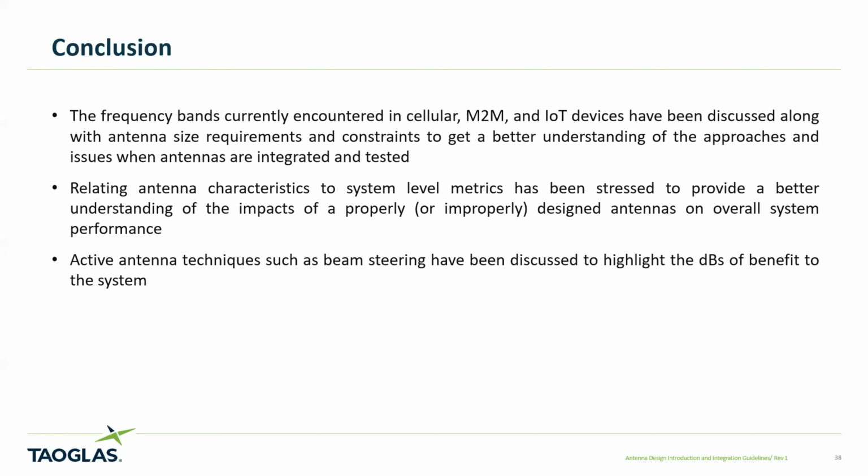I forgot the name of the technique. It's been around a long time, and it got revived again around 2008, 9, 10. You take two antennas sitting side by side, take a small amount of power from antenna number 1, couple it back into antenna number 2, introduce a 180-degree phase shift, and over a narrow to moderate band provide complete cancellation of that coupled component. So there are techniques out there, but then you just have to implement them.